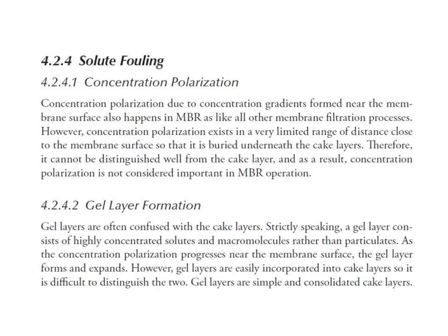Gel layer formation happens in MBR systems, and it looks similar to the cake layer formation. Strictly speaking, a gel layer consists of highly concentrated solutes and macromolecules rather than particles. So although it looks just like a cake layer, the composing material is solutes or small colloidal materials.